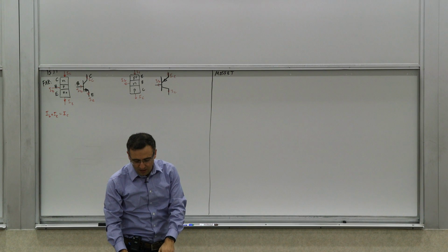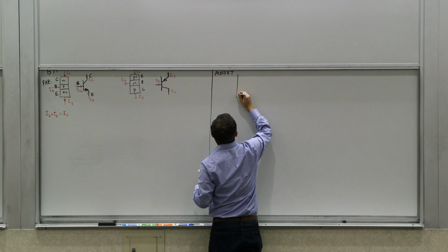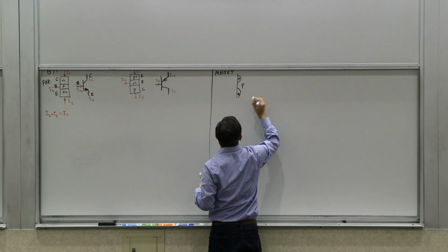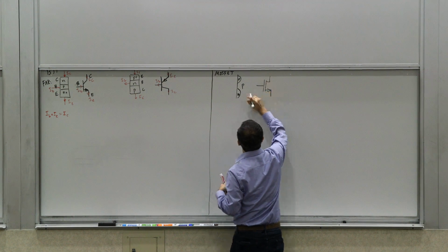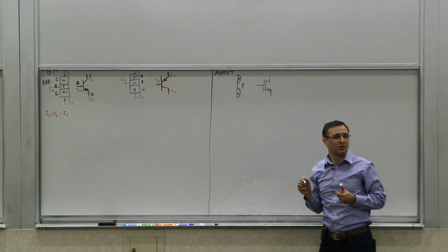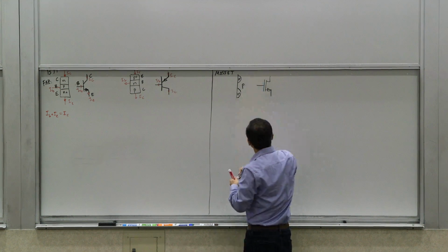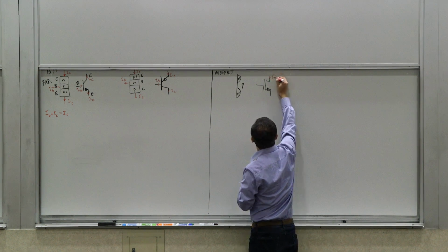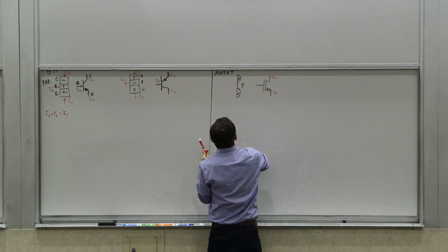So we haven't even started with that. So let's do the similar thing for MOSFET. So MOSFET, how does it look? And again, we have 2 types. We have the NFET, which is basically N plus, P, N plus, right? And you can draw it this way. Now, the way NMOSs are made, generally speaking, not always, but often, they are made symmetrically. So you can actually switch the 2 terminals. But at any given point in time, there is a certain direction of current flow. And for that direction of current flow, you have current going into the drain, coming out of the source, and then you have the gate, which I didn't show here in this picture.